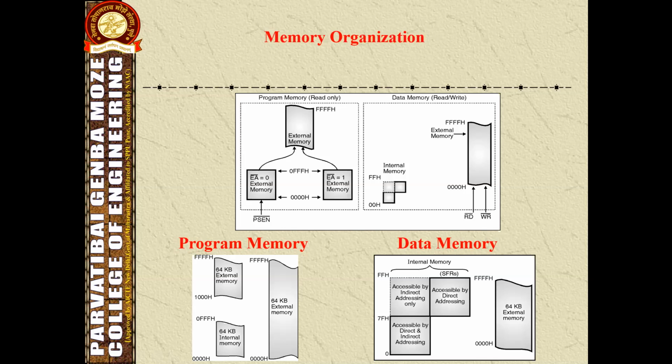From 00H to 7FH, the memory is accessible by direct or indirect addressing. And from 80H to FFH, this memory is used for the special function registers.